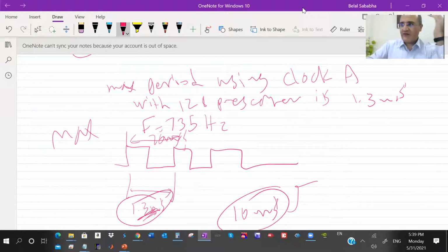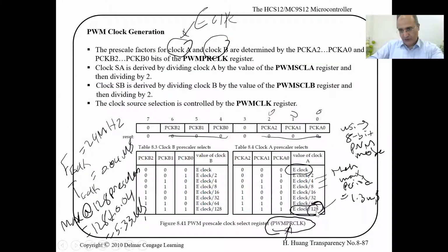We have several options. We slowed down this timer with the prescaler to the maximum. One option is to slow down the PLL clock, or take a sub clock.